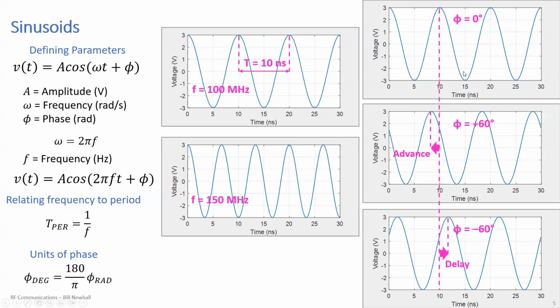So phase shifts also relate to offsets in time. So if you have a delta phase, delta phi here, you can relate that to delta t, the shift in time, by omega, right? Radians per second for omega times seconds for delta t is radians of phase. So those are the parameters we're talking about when we talk about modulating or demodulating waveforms, which we'll talk about next.